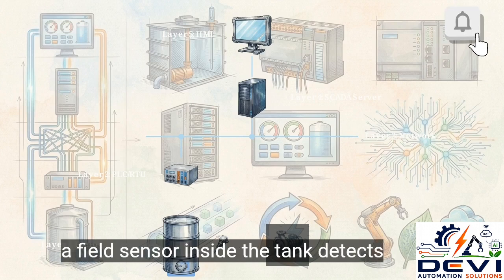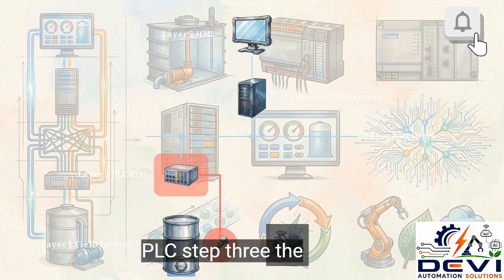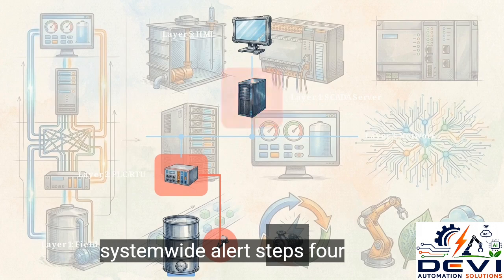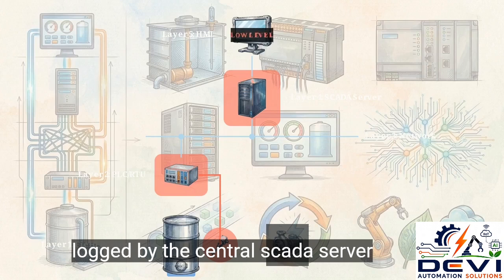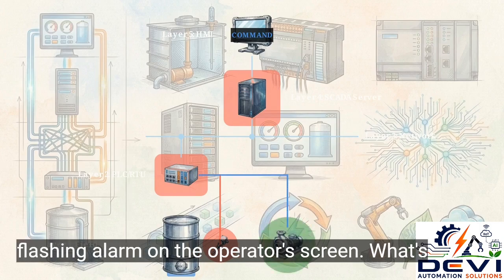Step 1. A field sensor inside the tank detects that the water level has dropped critically low. Step 2. That analog alert signal is instantly sent to the local PLC. Step 3. The PLC processes this incoming logic, recognizes the fault, and prepares a system-wide alert. Steps 4 and 5. The alert data transmits across the communication network and is permanently logged by the central SCADA server. Step 6. The server immediately pushes this data to the HMI, triggering a flashing alarm on the operator's screen.